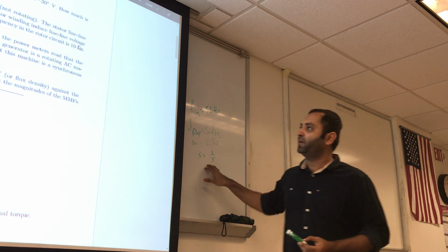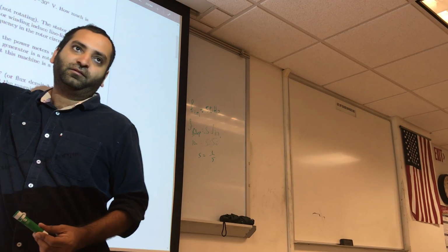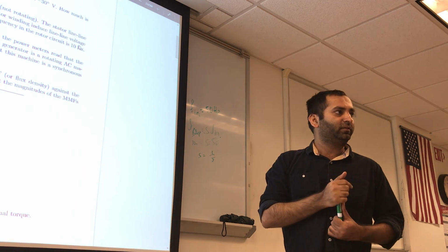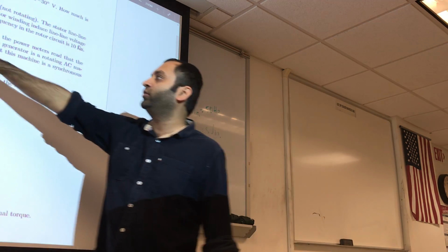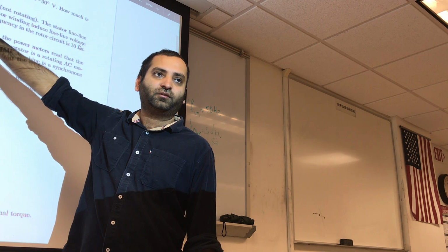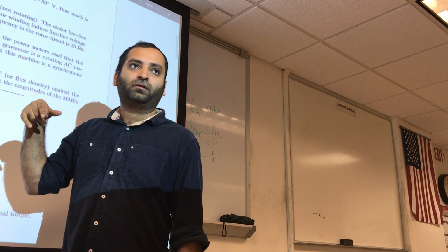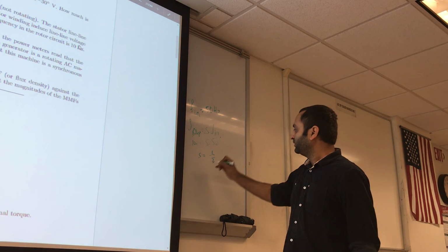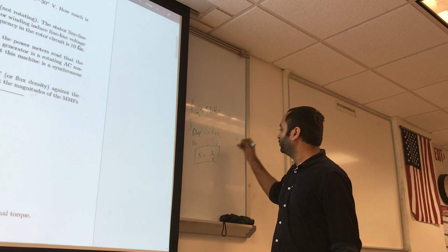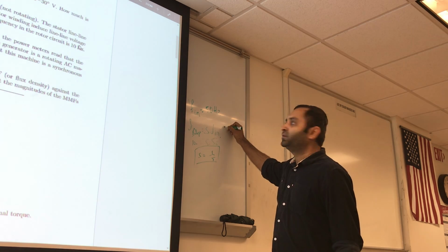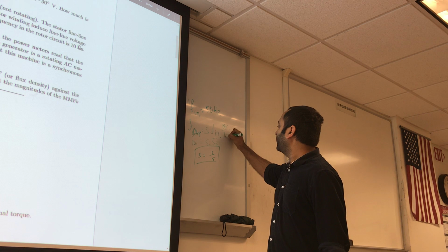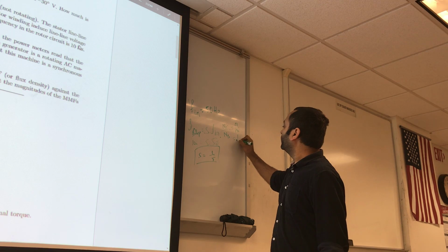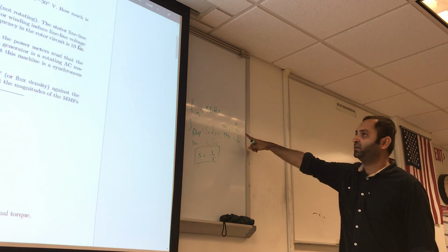So once you find the slip and you know the ratio is 10, you can find the rotor winding voltage. Is there any question for this? Do you understand how to find the rotor winding induced voltage? What's the next step after this? You have the slip now, and NR over NS is equal to 19 over 190, which is 1/10, right? So this is the winding ratio.